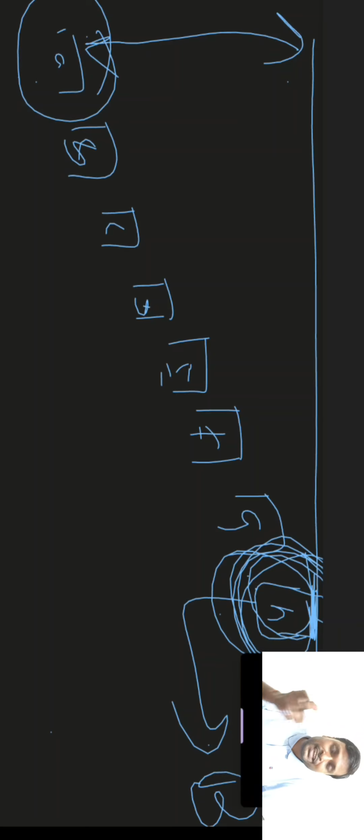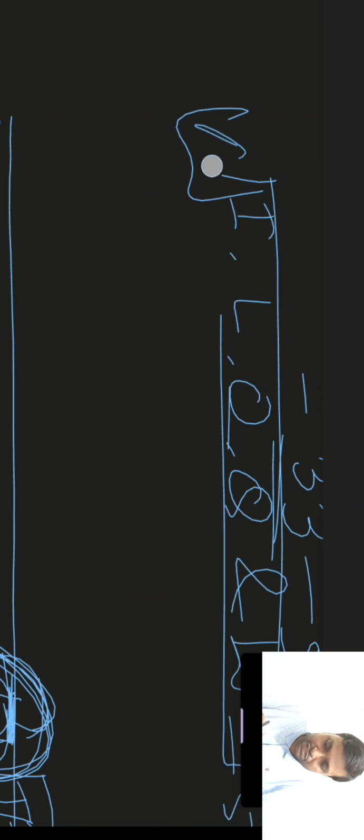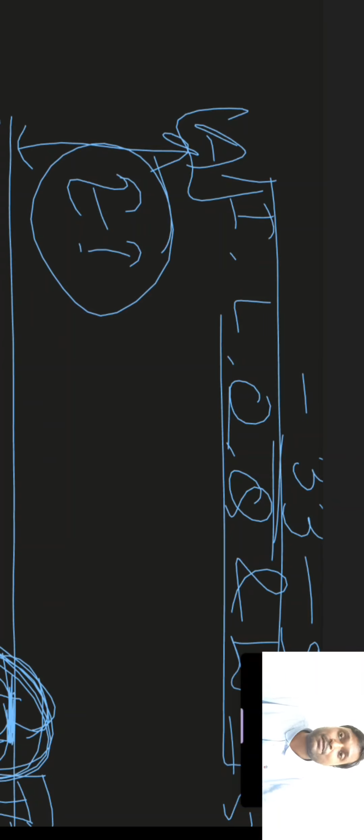In other words, we can understand it like this: the fundamental deviation for shaft is nothing but the écart supérieur. So the écart supérieur for shaft will be equal to, let the hole be here, the fundamental deviation is this one, and this is nothing but the écart inférieur. So the écart supérieur of shaft will be equal to the negative value of the écart inférieur of hole for the same type of fundamental deviation.